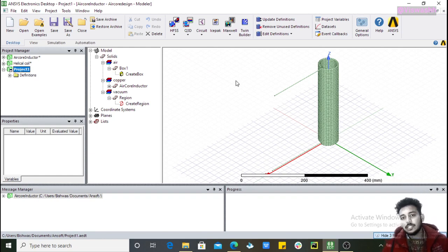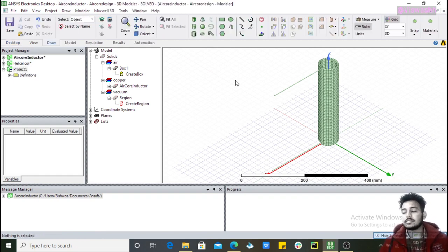Now, next thing is, because we are trying to design the coil with certain parameters, with certain physical constraints, the first thing we'll do is this is EDT, let me remind you again. Inside EDT, there are different types of packages, or you can say sub-simulators, sub-simulation software, and among them we are choosing Maxwell 3D because that's where we work. There is another type like HFSS, and there is another like Simplorer, nowadays known as Twin Builder. So there are multiple modules, and we are picking only Maxwell 3D. So make sure that Maxwell 3D is correctly installed in your system in Ansys.